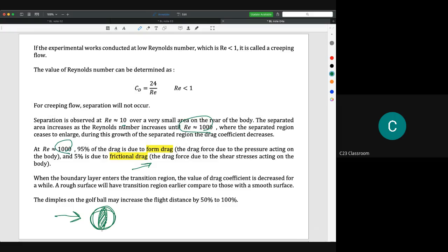So we know when there is a pressure change, and then the pressure acts on a certain area, so it will create force. And then the frictional force drag is actually when the flow goes from here to here. So when it's moving on the surface, it will give us the frictional force. So that's why in a boundary layer, because we are dealing with the drag force, we are dealing with the shear force only. We try to limit the resistance that occurs because of the cross-section area.